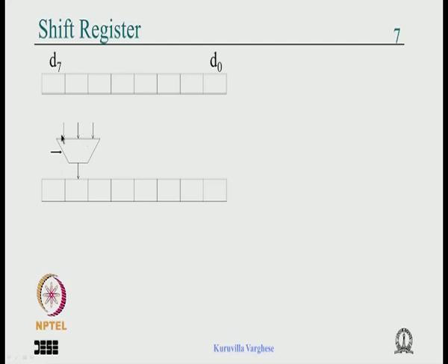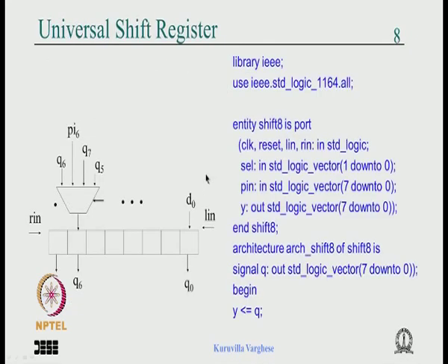And there is a select line depending on the number of paths, and this is replicated. So you have an 8 bit register, then you have 8 muxes. I said you can view it as 8 separate muxes or a huge mux, it depends how you view it, and the coding also can be different depending on that. So the variable shift is done through a multiplexer.